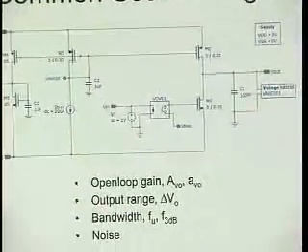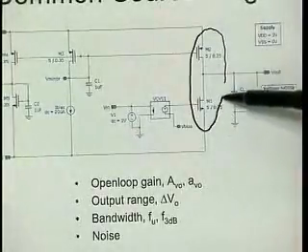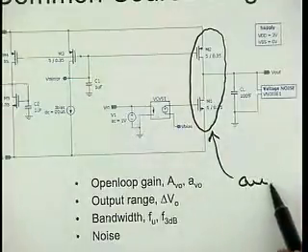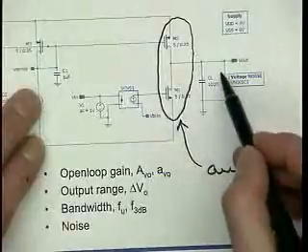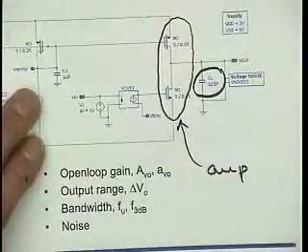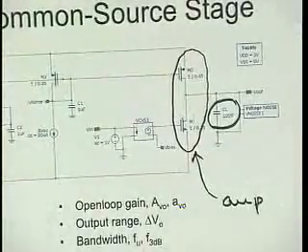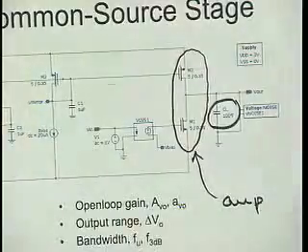The amplifier is very simple. This is the amplifier here. This is the actual amp, and the whole rest is just, this is the load, of course. Very important that we always include a realistic load when we characterize an OTA, because the results depend a lot on the load, right? And so if we leave that away, we kind of have to start all over when we finally figure out what it is.